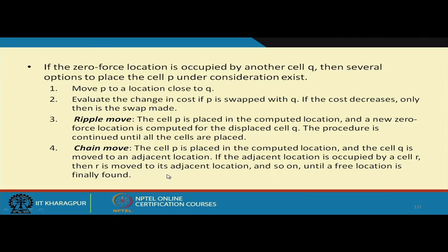So, we have seen force directed placement and constructive placement, where using an analogy from springs, the way forces are exerted by springs on a body, we can also find out the best location to place the blocks. Now, there have been a number of such placement tools which use this kind of heuristic based on force directed placement to actually find out the location for the different blocks.